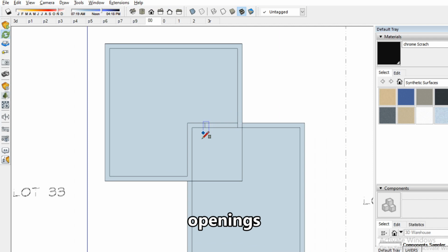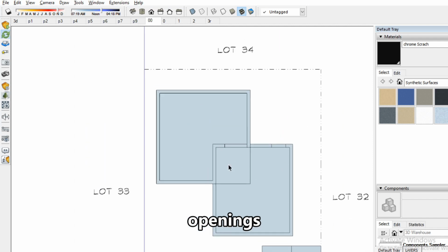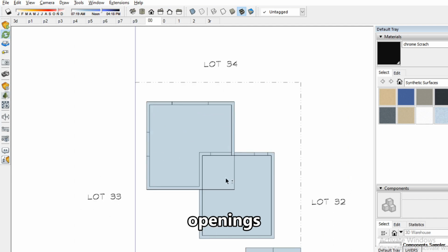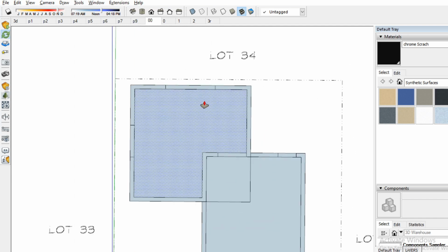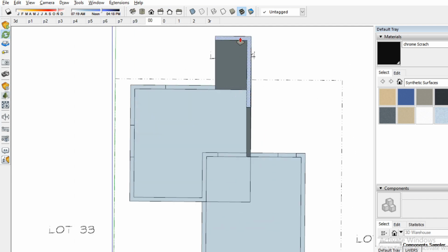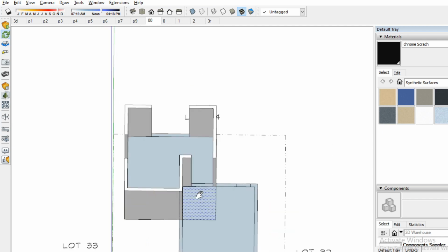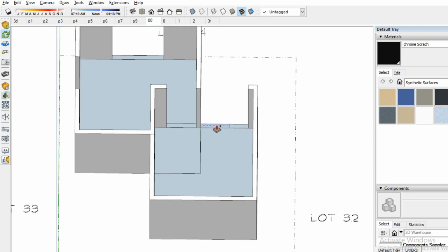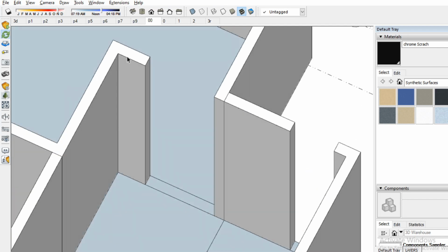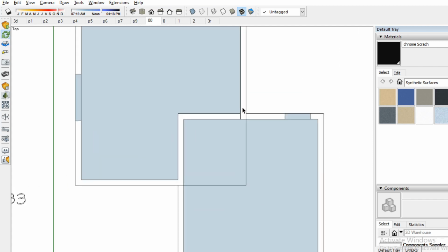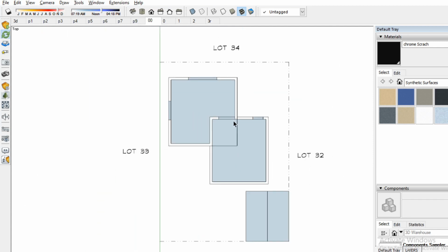Say we have openings later on. You could indicate them here in the plan. However, it would be better to see them in 3D later on to align them. Using the Push/Pull tool, enable Ctrl to have a fill below the solid. Don't worry too much about filling these gaps later on, so that you could still see them in top view even without the section cut yet.